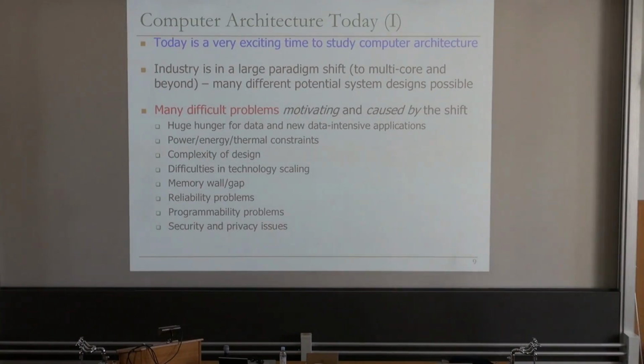Okay, I'm giving you a lot of things very quickly, so feel free to stop me if you have questions. But the next one is memory wall and gap, which we're going to talk a lot about. There is a fundamental disconnect between data storage and access and computation today, and that disconnect is growing. Even though processors may not be getting faster, in the past, processors were getting faster, much faster than DRAM bandwidth was increasing. I think that has changed. Processors are getting not as fast.